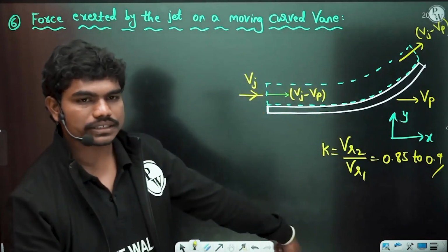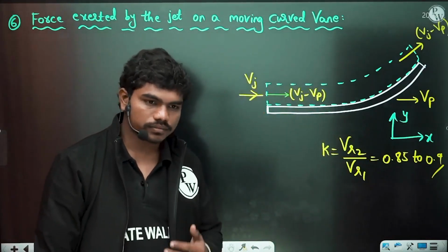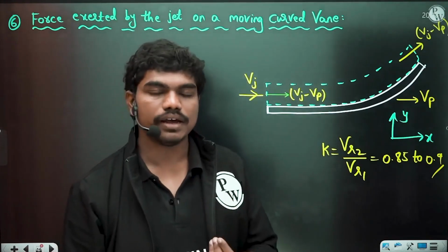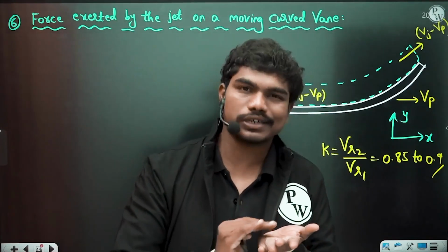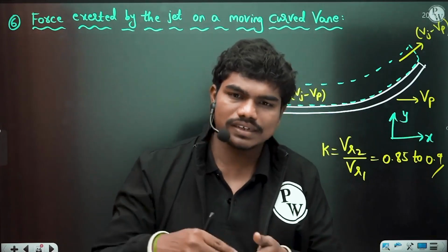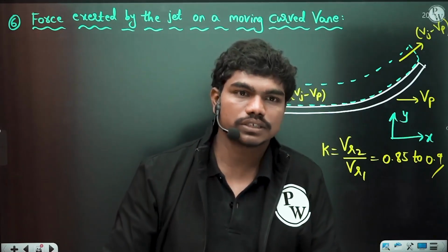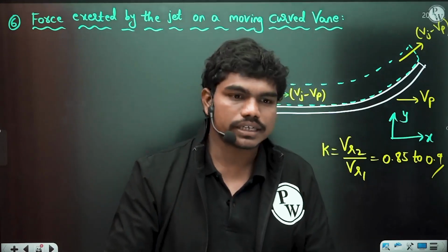Normally you might have seen this, because after certain usage, because of the high velocity impingement of the liquid, the blades get eroded slightly. Because of that, over a period, on the top of the blades there is something called pitting, which is called surface failure. Have you heard this word pitting?